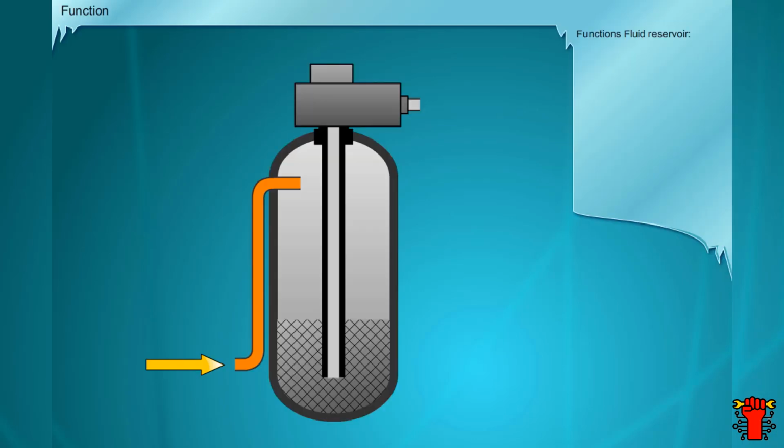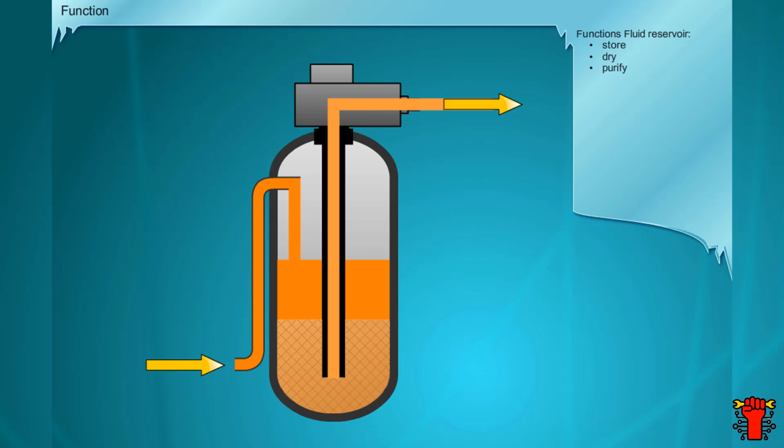The refrigerant from the condenser enters the fluid reservoir. It is buffered in the refrigerant receiver. The fluid flows through the desiccating filter layer. Undesired particles, such as abraded matter, are retained to prevent damage in the refrigerant circuit. In addition, the filter medium is capable of chemically absorbing moisture. The dried and filtered refrigerant is directed upward in the ascending pipe and leaves the reservoir heading toward the expansion valve.